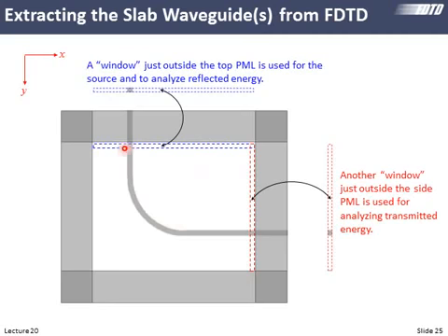So what we'll do is we'll look at this little window in the cross-section of our grid. And this is what we'll analyze in our finite difference method. We'll look at that cross-section and calculate all of the modes that exist. And we'll use that to source the waveguide.